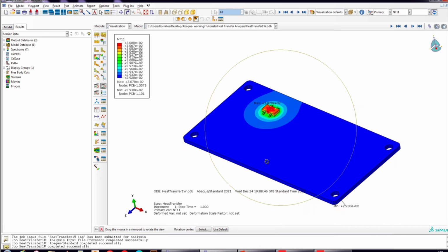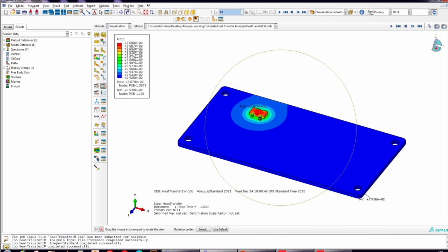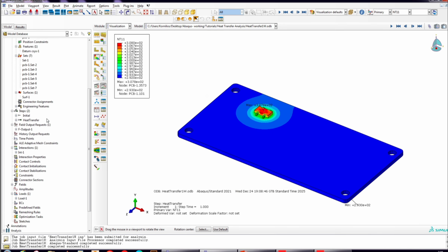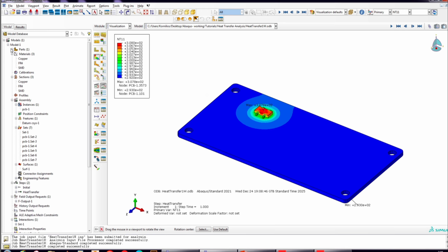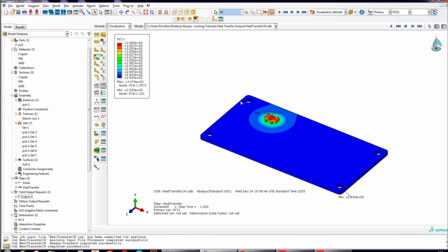Okay guys, this is a complete heat transfer analysis including both convection and conduction modes. The interesting part was the partitioning of the PCB, which is a computationally efficient way to simulate the traces and include both the copper and the dielectric FR4 materials.